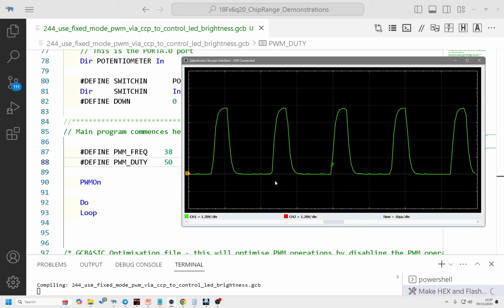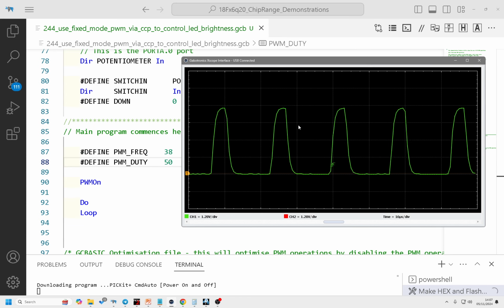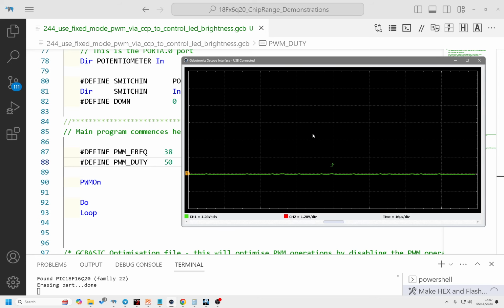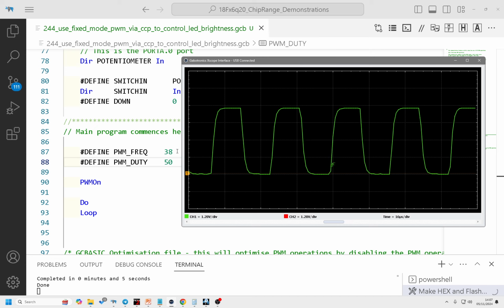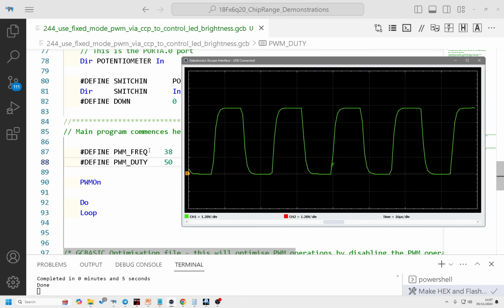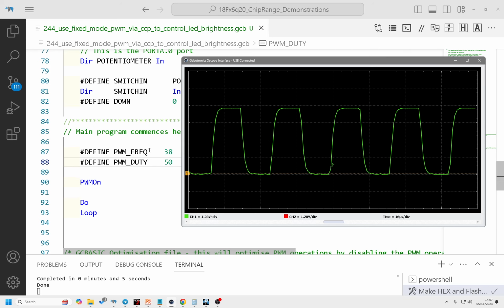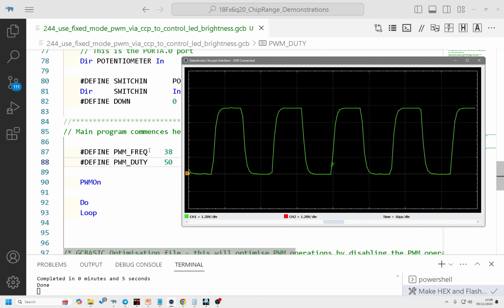And we'll see it flash, drop down, and then go back to the signal we're looking for. So that's just PWM on. I mean, that was simple. Trust me, you don't even need these 2 constants. They are automatically defined. So if you want 38 kilohertz, you just say PWM on once you set your PPS. On this PPS chip, you have to set CCP1 to make it work.